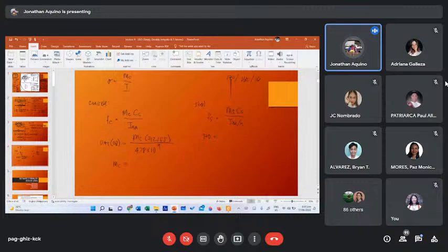Anyway, as long as you specify in your solution that you use 170 or 165, any assumption will do. But you cannot say grade 60 and then use 140 megapascal. Of course, that is wrong because 140 is for grade 40 reinforcing bars. So 170, okay, Ms or moment capacity of steel times Cs.